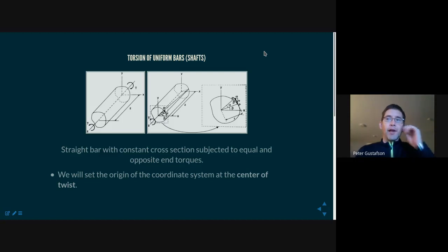when it is deforming. The equation related the centroidal deflection or displacement. Deflection is inherently for a beam at the centroid, whereas displacement could be anywhere in the beam. But looking at the deflection, we were able to write the displacement everywhere in the beam based on some simple assumptions of linear kinematics for an Euler-Bernoulli beam.